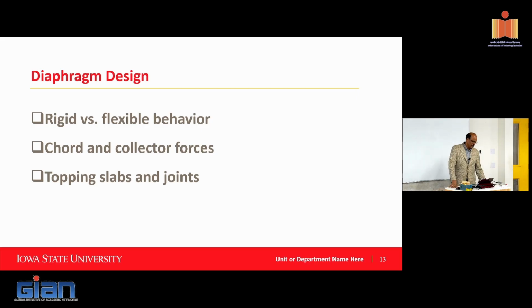Again, work has been done in this space, typically to make sure that the terms that you'll see here, chord and collector forces, depend on how the force gets transferred. If you take a seismic event, you get the inertia force created on the floors because of their weight, which has to be transferred from the slab to the frames or walls supporting the structure. And whether you collect the forces and transfer them, or you act as a chord, which basically has a strut to transfer the forces, it all depends on how you conceptualize this.